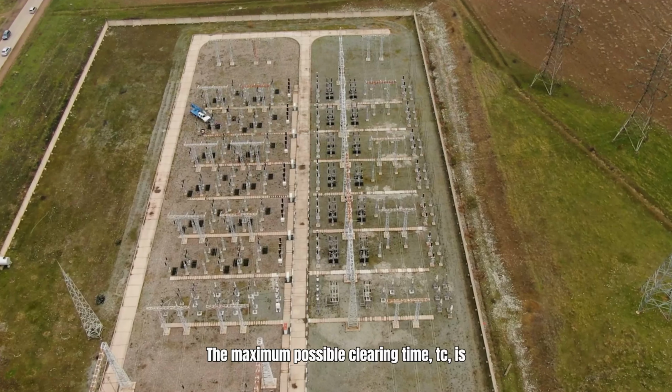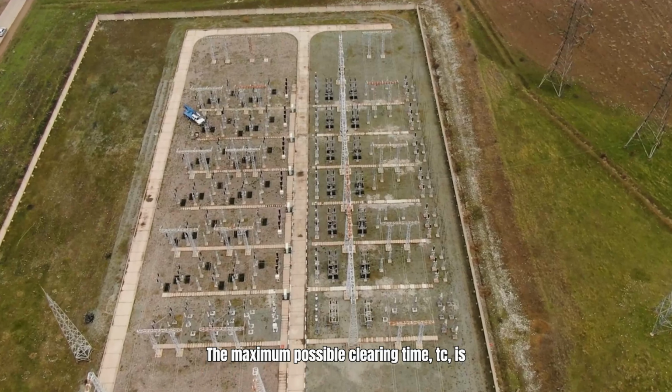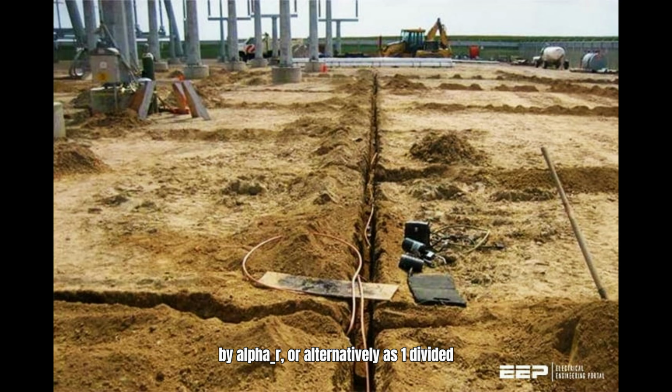The maximum possible clearing time, Tc, is conservatively taken as 1 second to account for protection system response in real-world scenarios. TCAP is the material-specific thermal capacity factor sourced from Table 10.1, quantified in joules per cubic centimeter per degree Celsius. K0 is mathematically defined as 1 divided by alpha_r, or alternatively as 1 divided by alpha_r minus Tr, expressed in degrees Celsius for thermal modeling. Tr serves as the reference temperature for all material constants, ensuring consistency and reliability across the entire set of grounding calculations.